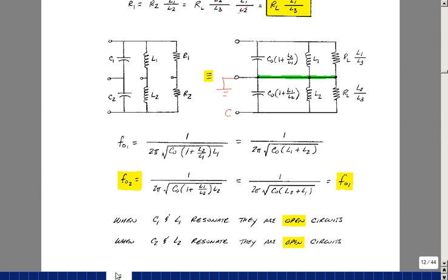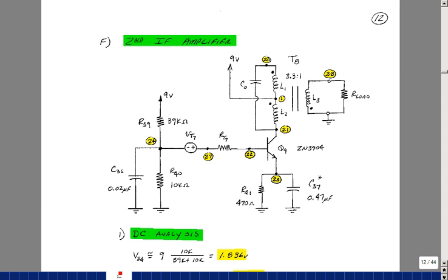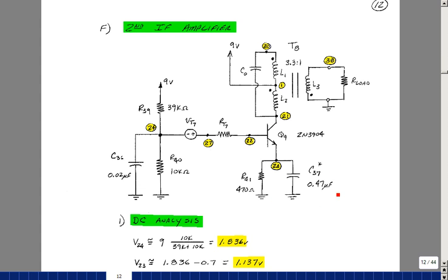So if we go to this page then, for AC, this will be a short circuit. This will be a short circuit, so these will get shorted out. Just have this voltage source and resistance here. In the actual radio, there was a smaller value of capacitance here. I think you need to increase that capacitance by at least a factor of 10 or 20. The value's on the bottom of the page. So this does look like a short circuit for AC.